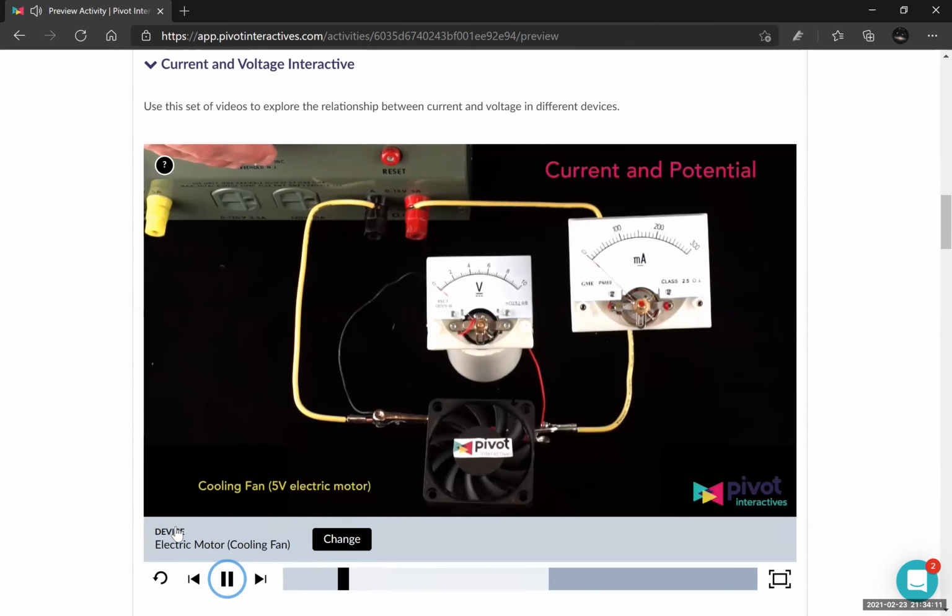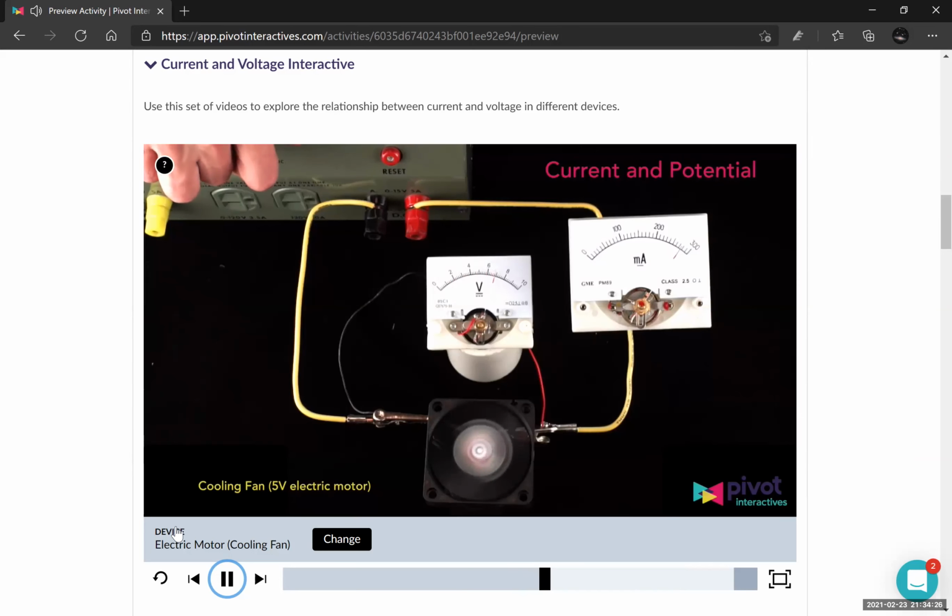Once you start turning the voltage, see how the current changes, make measurements of voltage versus current, and see what you get. Is this ohmic or not? Look at the graph, the type of shape you get, and the resistance value, and all of those things.